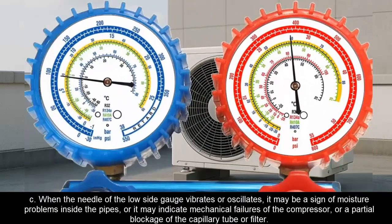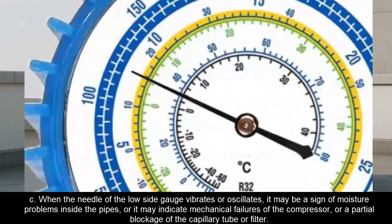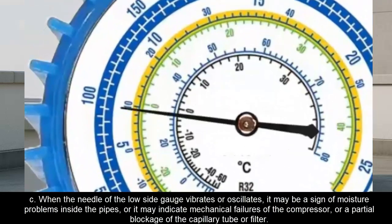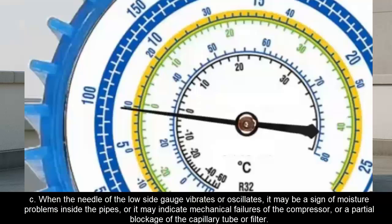C. When the needle of the low side gauge vibrates or oscillates, it may be a sign of moisture problems inside the pipes, or it may indicate mechanical failures of the compressor, or a partial blockage of the capillary tube or filter.